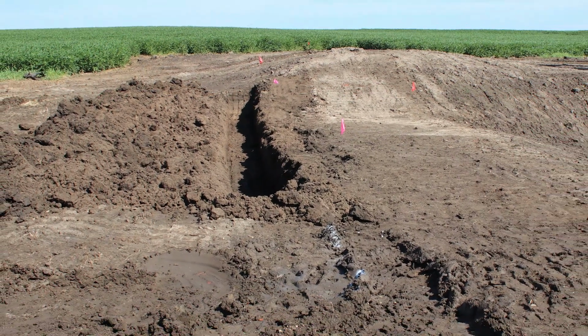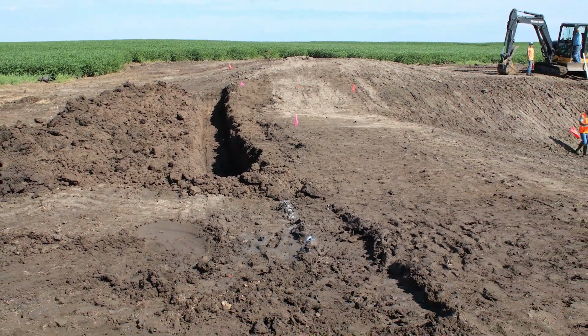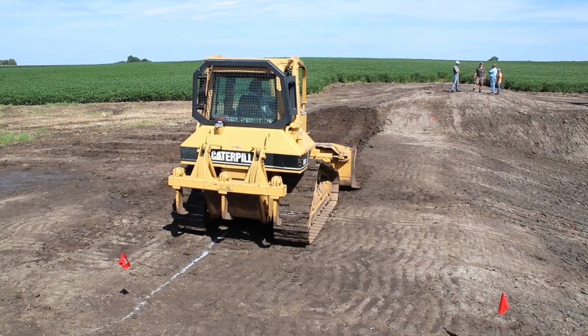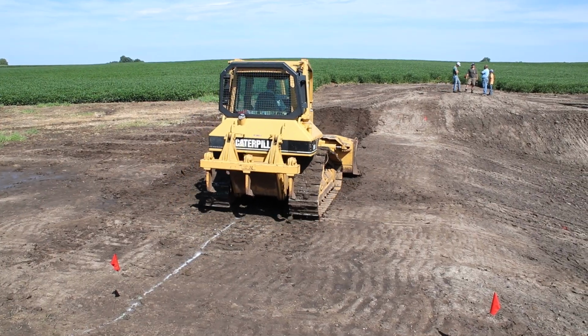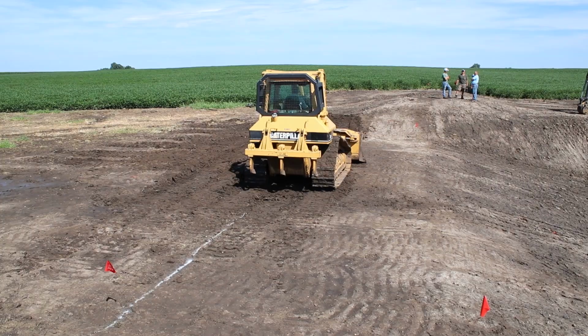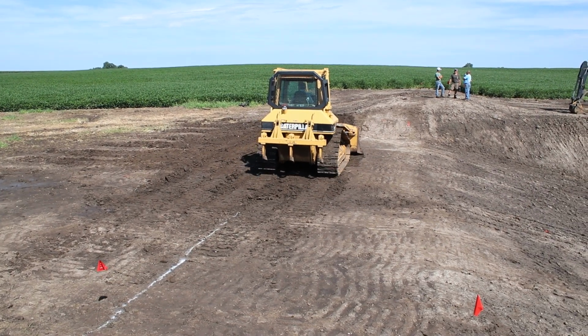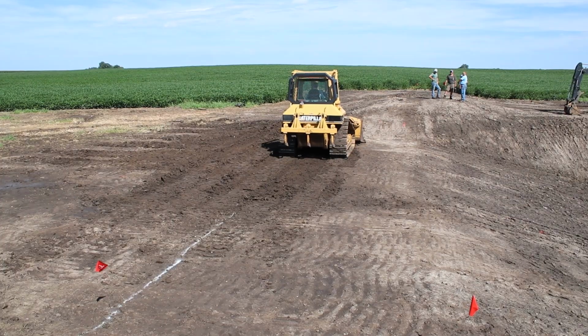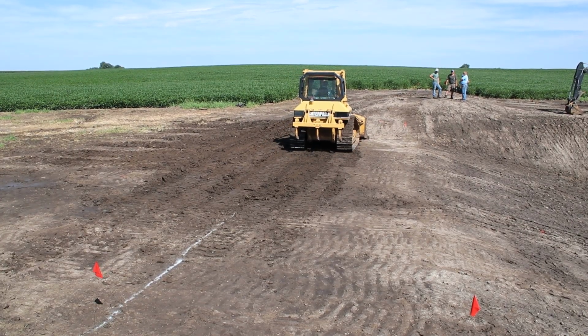Survey shots were taken to make sure everything was laid out according to the design. When they did this, they discovered the inlet trench wasn't exactly perpendicular to the slope. So, they decided the trench needed to be backfilled and re-excavated, making sure it was laid out as in the design and perpendicular to the slope. Starting out so everything lines up as laid out makes installing each roll parallel to one another much easier.